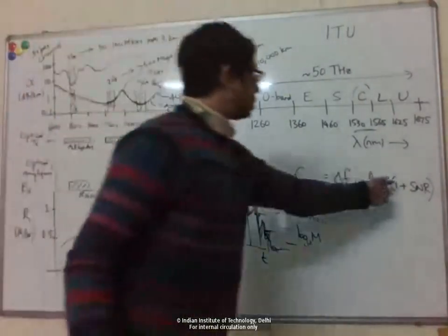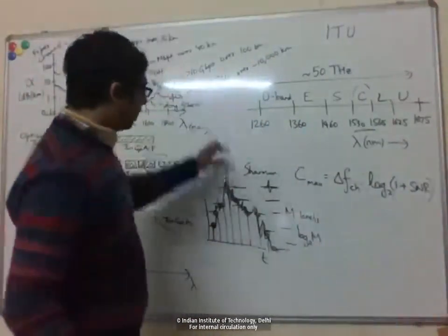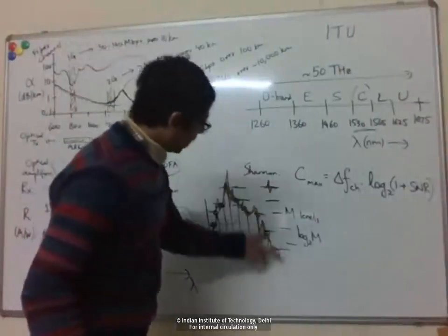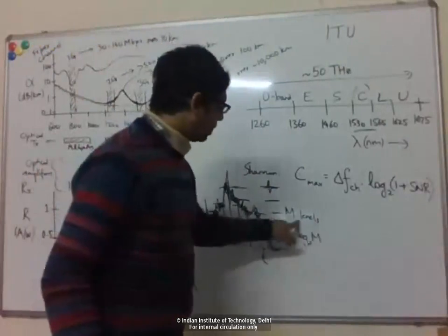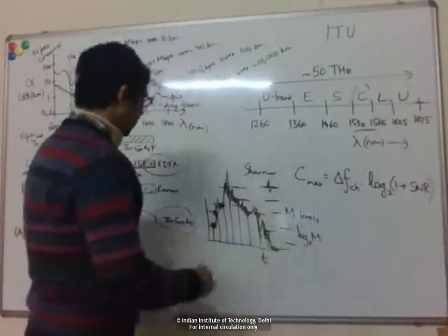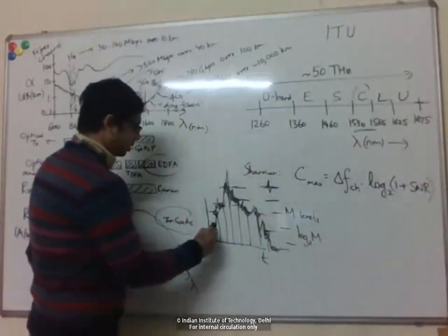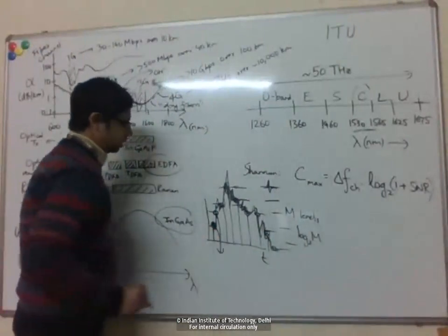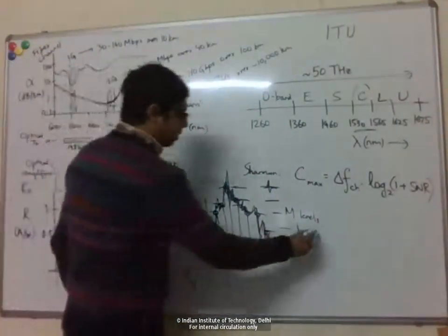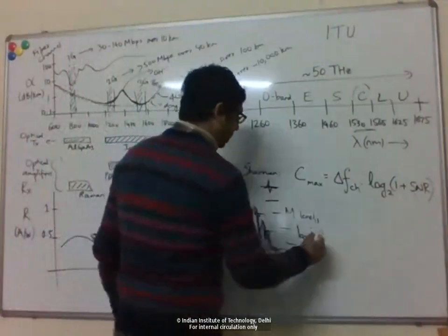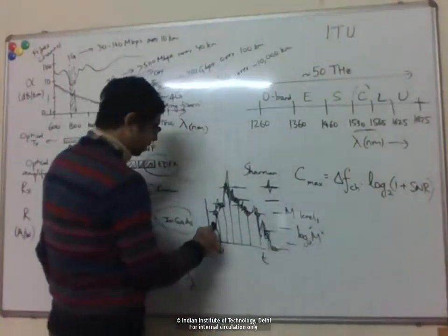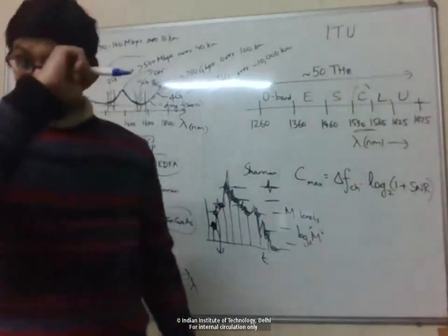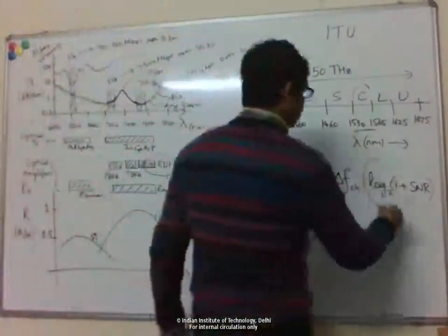So the higher your SNR, which means the higher the signal level compared to the noise, the more levels I can quantize it into, which means I can send more bits. So for each symbol here, if SNR is higher, m is higher, and log m, the number of bits that I send per symbol, is higher. So that is what this thing is.